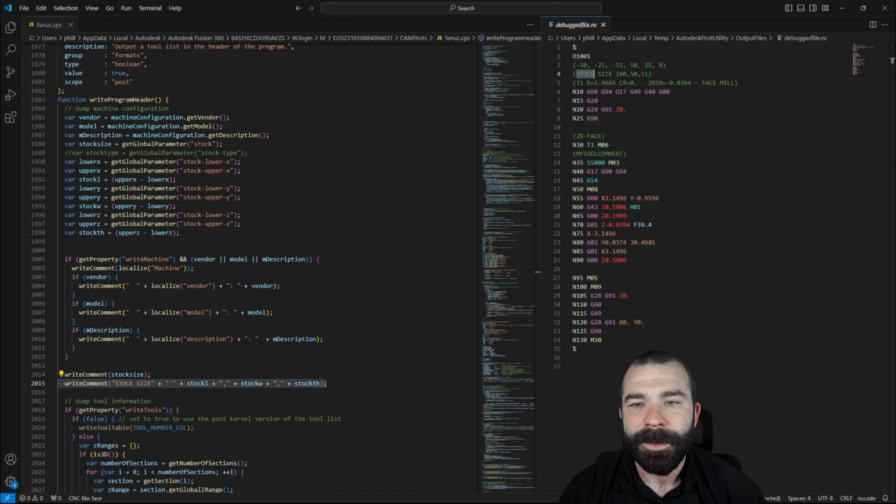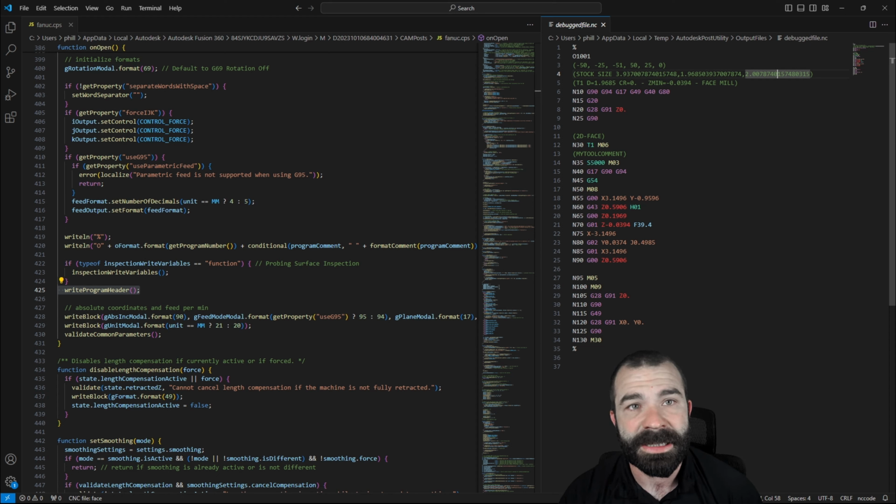Again, hitting save. As you can see now, we have 3 sets of numbers that are just massive decimals because of the conversion. This was the next thing a lot of guys came back to me on and said, hey, I want to shrink this up. Or if you're spitting out full numbers outside of Fusion, it'll actually come in as that whole number in your stock field. Just to make life easy, let's do a precautionary thing. We're going to set a format on these numbers so that they only display 3 decimals or 4 decimals, depending on what you're doing.